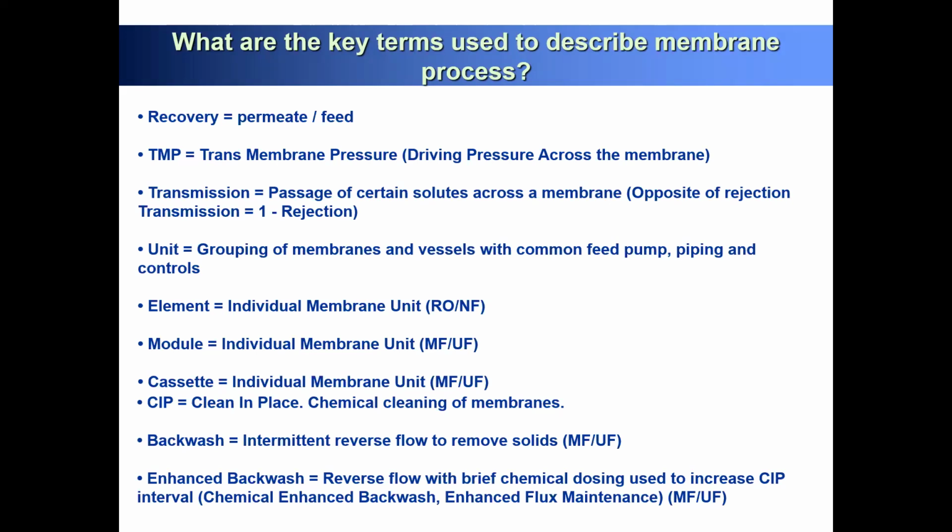So you have a higher recovery, you will have a more efficient operation without any fouling issues, right? So how we can manage this recovery? So that's very important. Recovery is equal to permeate over feed. So you can decide depending on your salt concentration, also your inorganic scaling, your fouling issues.